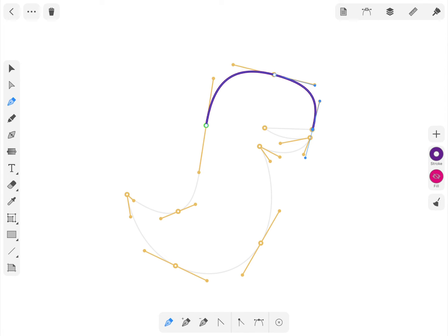To overcome this, use the Convert to Corner Points tool on the control bar. Just tap on it to convert the selected point into a corner point. Then we can continue drawing with the straight line. Tap once without pulling out the direction lines. Move on to another point, tap and drag to create the curvature of the lower jaw. As always, make sure the length and direction of each handle corresponds to the auxiliary lines.